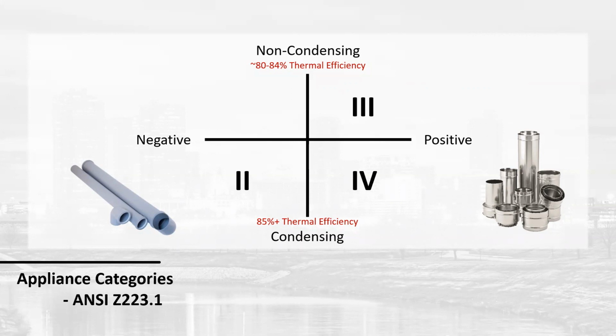So many engineers respond saying that, yeah, that's why we only allow CPVC. And yes, CPVC is a higher temperature. It's about 190 at atmosphere. But in order for a boiler to be installed with this product, with a non-listed product, they have to have some type of limiting device in their boiler that if the boiler flue temperatures start to exceed what those limits are, it'll actually either shut down or detune the boiler. And typically this is going to happen in colder climate months when you need the boiler the most. Those flue temperatures start to increase, and then it'll start to detune the boiler.